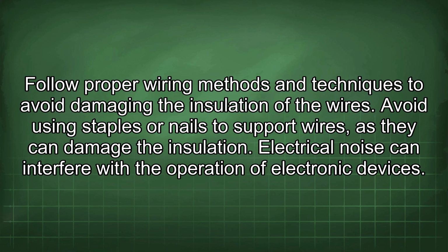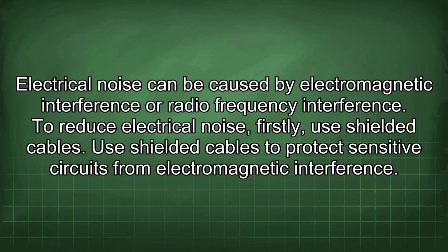Avoid using staples or nails to support wires, as they can damage the insulation. Electrical noise can interfere with the operation of electronic devices. Electrical noise can be caused by electromagnetic interference or radio frequency interference.